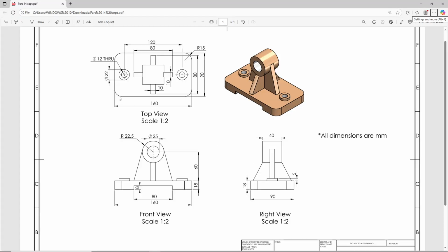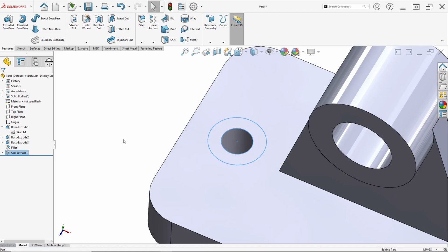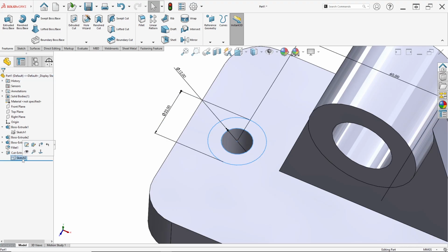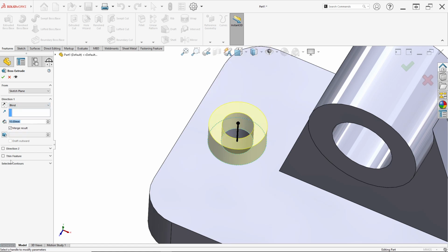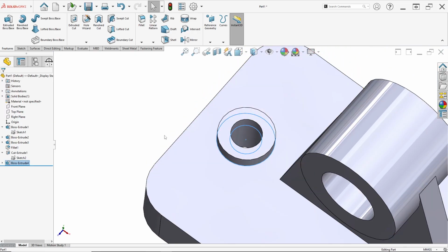So then we can extrude boss in here, the outer circle of 22 millimeter, have thickness 5 millimeter. So we can see the sketch, click sketch 2 like this and click extrude boss or base. For direction, change to blind. And for select contour, we can click section, ensure you select here. And for depth or height 5 millimeter for thickness. Just click OK. Like this.